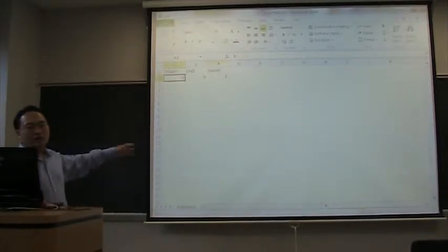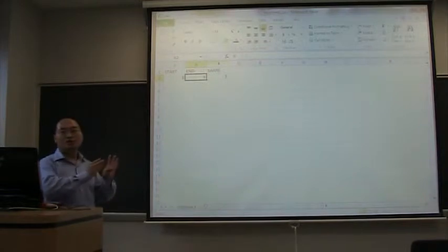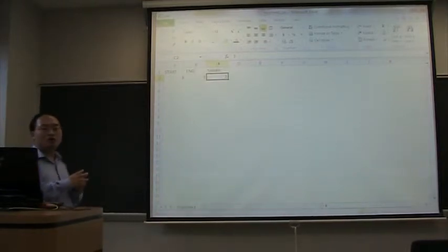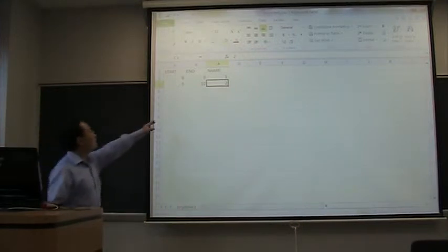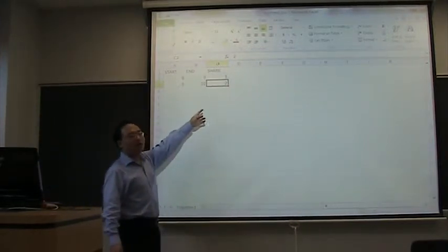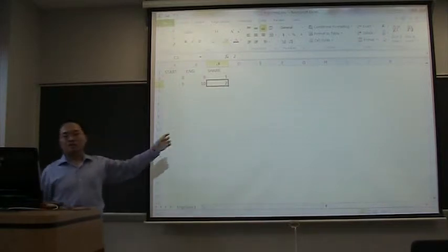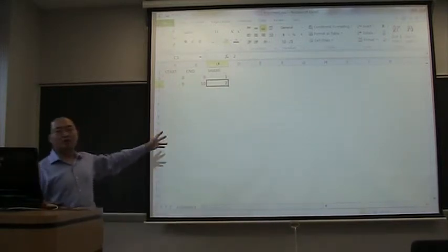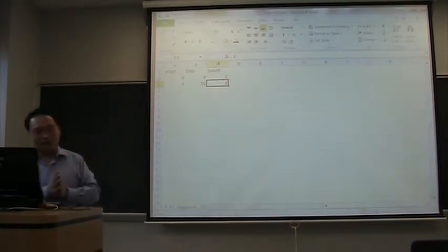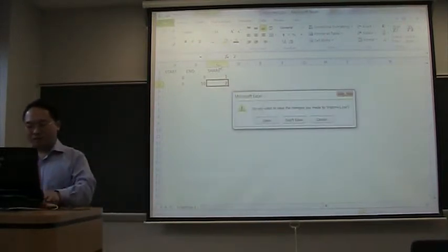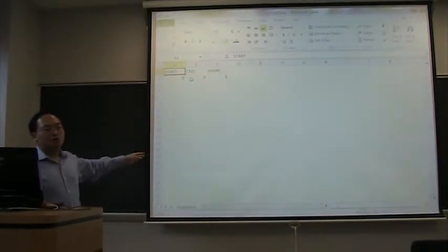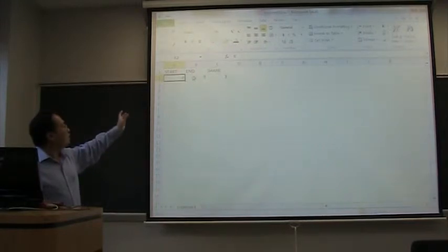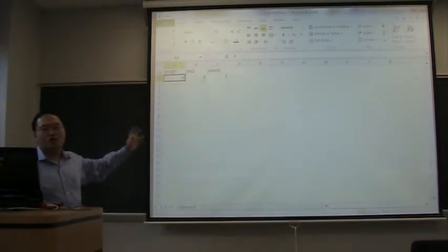It has a start and end, which indicate 2 time points. And the share means the relative proportion of the trips happening. For example, if I have 8, 9, 1 and 9, 10, 2, this will indicate there are 2/3 of trips happening between 9 o'clock and 10 o'clock, and 1/3 of them are happening between 8 o'clock and 9 o'clock. But in today's demo, I just use one line, which specifies between 8 o'clock and 9 o'clock, the share is 100%.